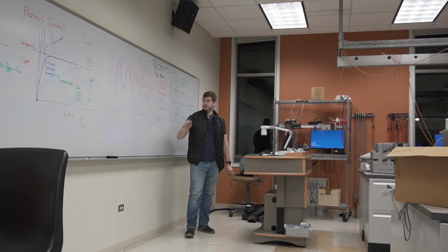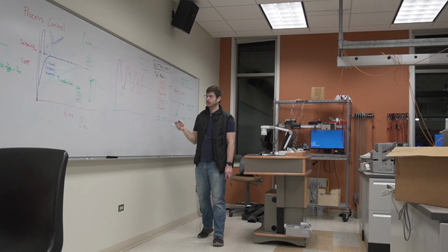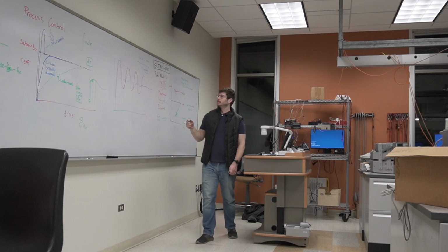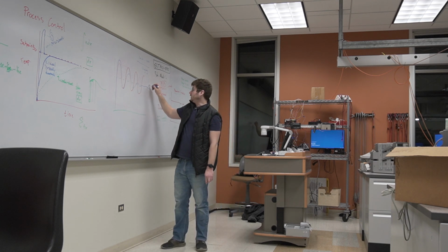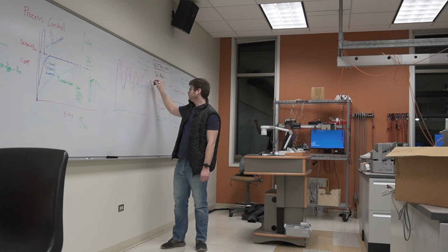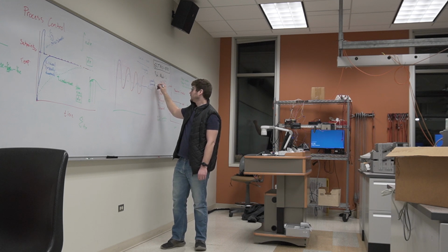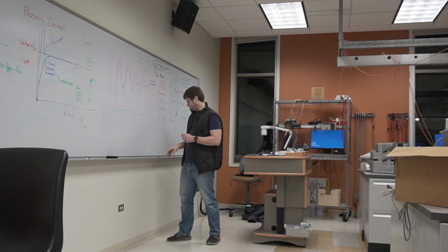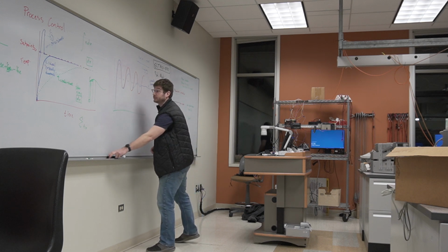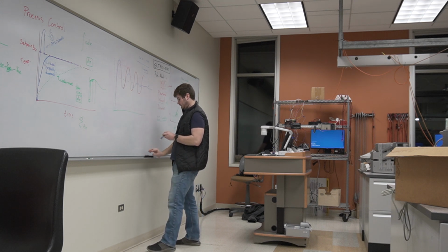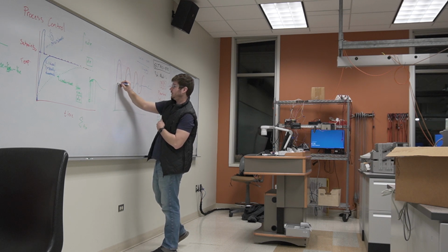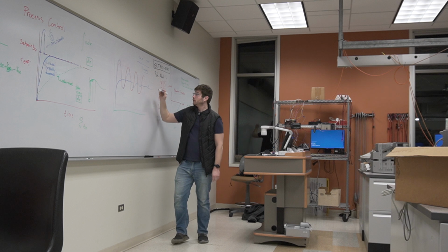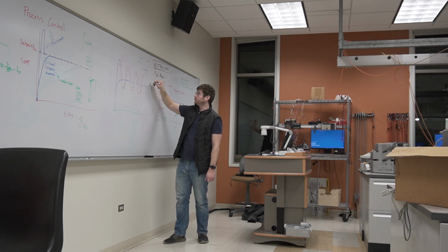Ringing, when we try to reach a set point and we kind of ring around it. It just also looks like a waveform for a ringing sound, right? This is said to be an underdamped system, okay? Or actually, that wouldn't be ideal. Critically damped is if it would really nicely sidle up like that. You could call this well-tuned, really.